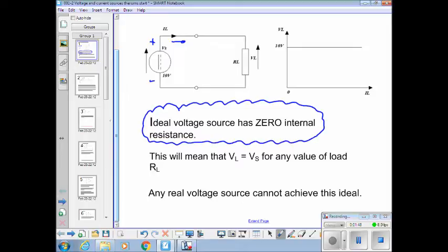As you saw last week, as you load your signal generator in the stop zone of your filters, your input voltage starts to drop. And if you put the lights on in your car and then try and start it, what happens to the lights? They go dim. So there isn't an ideal voltage source that exists out there. We can try and make one look like it, and we can model what a real voltage source does, and that's what we're going to talk about now. So, an ideal voltage source has an internal resistance of 0.